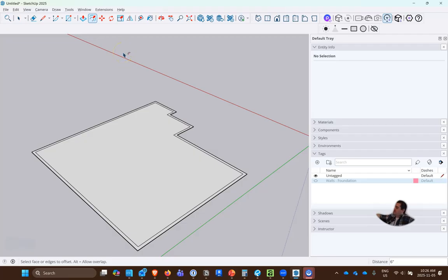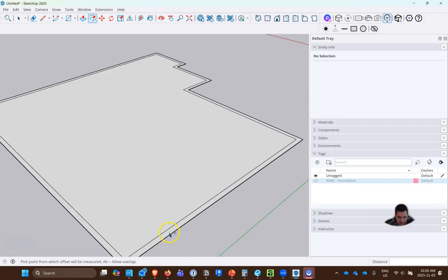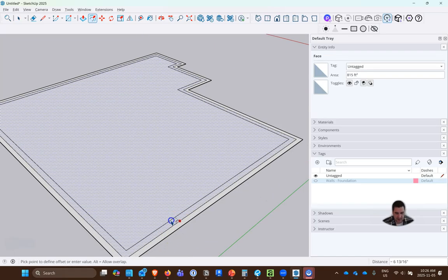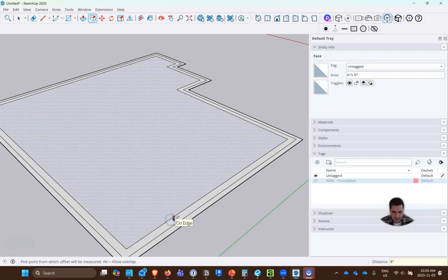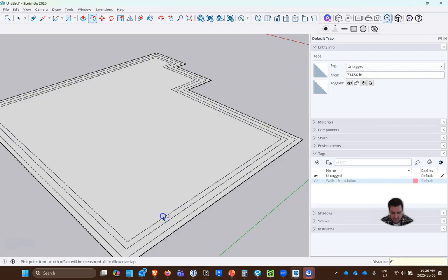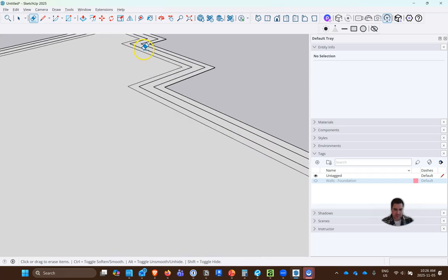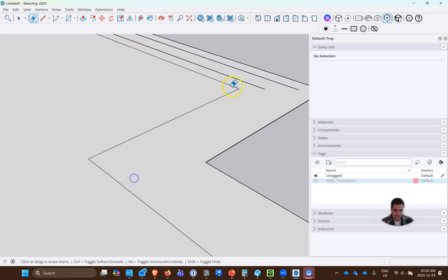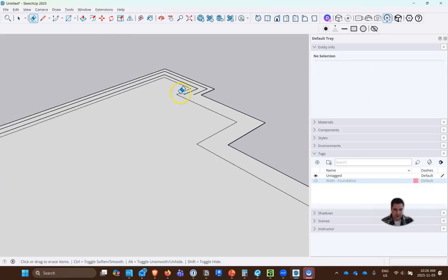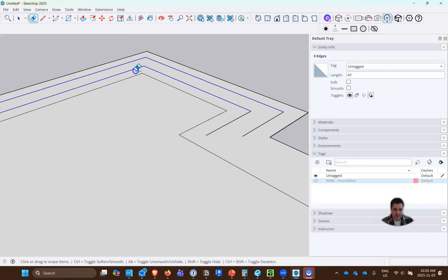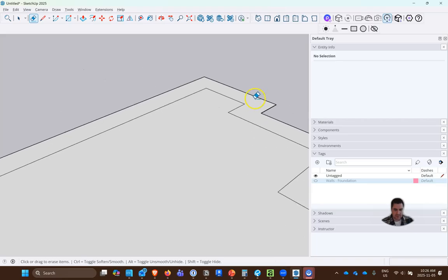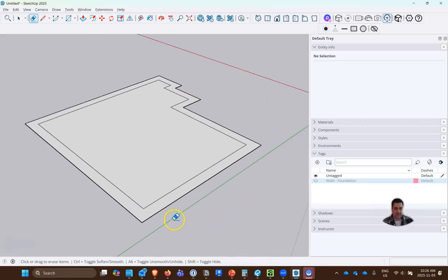I traced the outside of the walls, so we're only offsetting 6 inches outwards. But for the inwards, we can offset 8 then 6. Yeah, so to your point, I could do that. So we'll offset in 8, and we could offset in 6. And then what I want to do is actually delete these interior walls because we don't need them anymore. We do have to do a few more lines on the interior, but this gives us a pretty good basis to start. So that's kind of the perimeter of our footing.